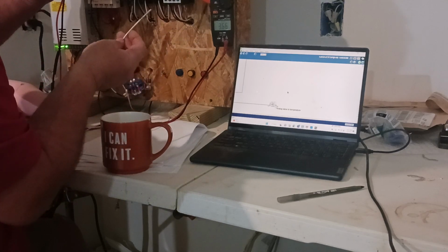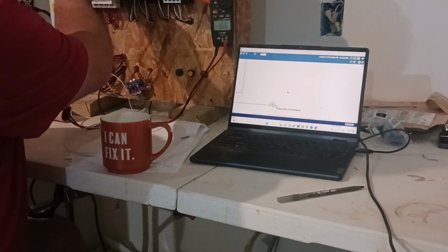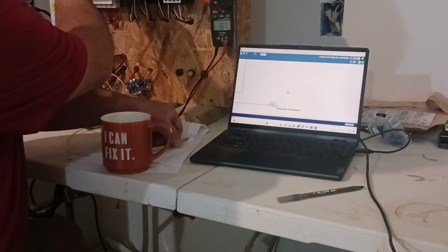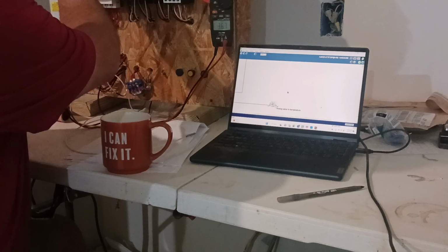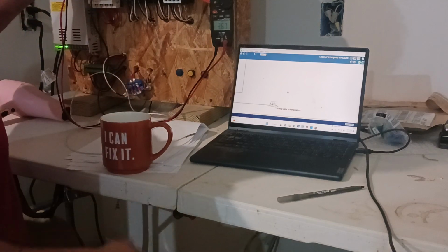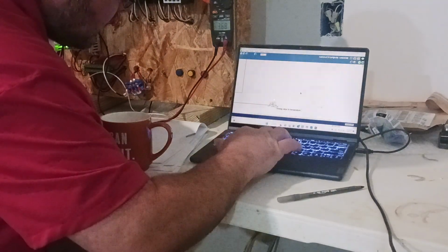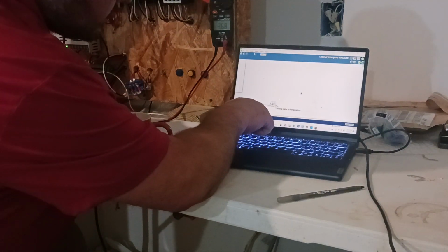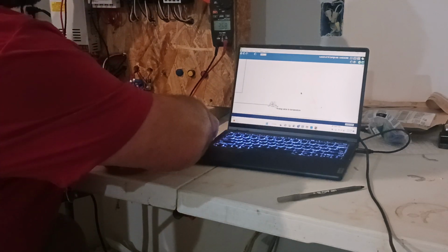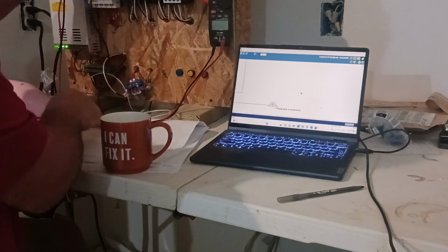365. So as I keep that out at room temperature, you'll notice this voltage goes up as the temperature sensor adjusts. It's just adjusting the resistance. So we're back up to 367, and our analog value is 93, and our temperature's up to 66, and eventually when this warms up, it'll get to about 78 in this room, right?